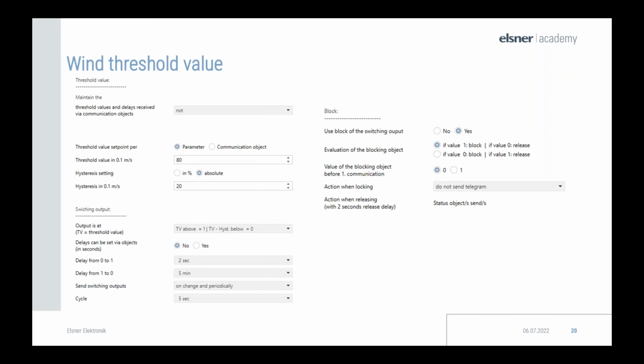This is very important because once again, just because there's a slight difference in the wind speed, you do not want your whole facade automation to move. You want to have it for a longer period of time to really say, okay, there's a longer calm without any danger. I can put the blinds down again. So you should not be thinking about it. Your building, your project should be thinking about it. That's why you have a very smart weather station. Okay.